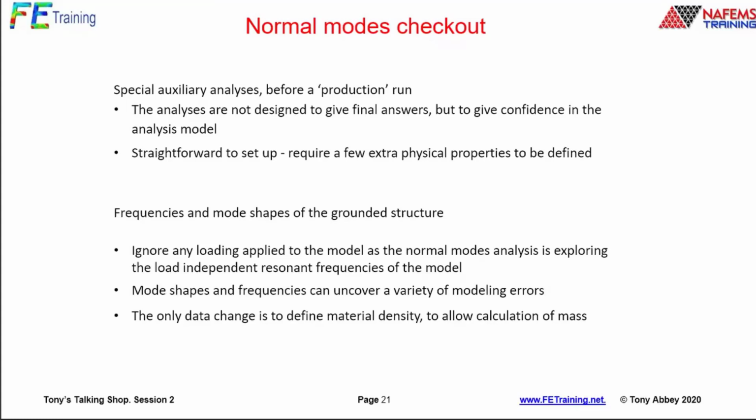I don't know how to set these up. Well, every single user interface I've seen, as long as you've got the boundary conditions set up, that's the constraints to ground. You don't need the loading. You've got the right physical properties. You've got the mesh there.